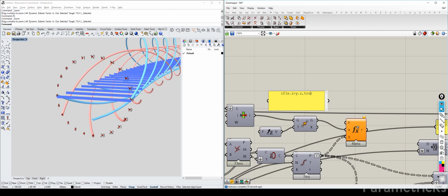So if you type true, meaning if this expression equals true, then the result will be true. You can also say give me a number instead, which is fine. This is basically an output if the condition that we've defined here validates to true, returns true. So we can say if the z of x is bigger than the z of y, then it's true, otherwise it's false.